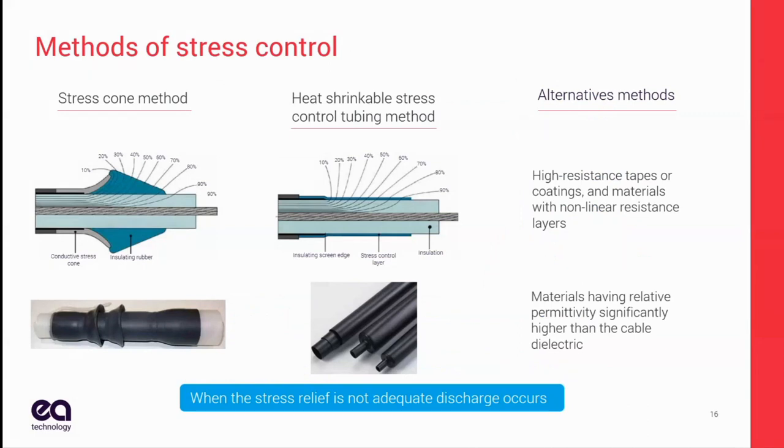And if you go to Amazon and you buy a Raychem termination, and it comes with a 4-page instruction sheet, and you go and say, okay, I can do this. And the instruction sheet says clean cable as usual, or strip semicon layer back cleanly. What does that mean specifically? It means something different to you than it does to me, and that's where we get ourselves in trouble.